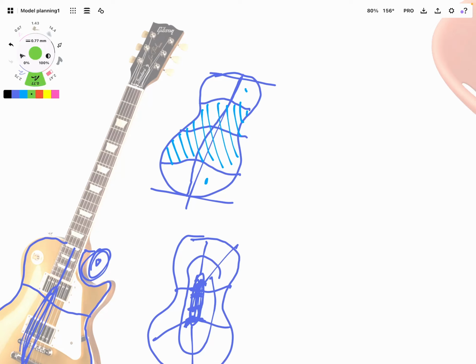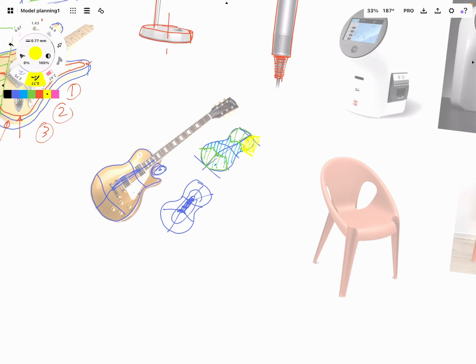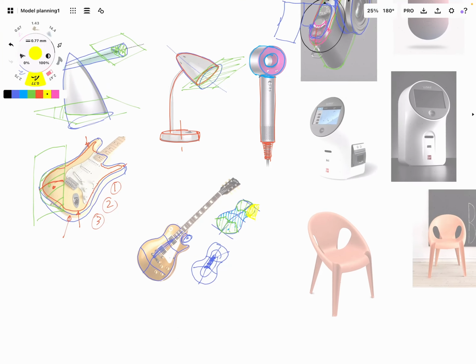So what we'll do is we'd go in and trim these areas. So if I erase that, okay, so now we could build a four-sided surface in here, as you can see. 1, 2, 3, 4. 1, 2, 3, 4. And we also use the center line, and that fills out those ends there. Okay, and then the last thing you do is you just drive a cut through here to create your cutout. Okay, covered that one, I think.